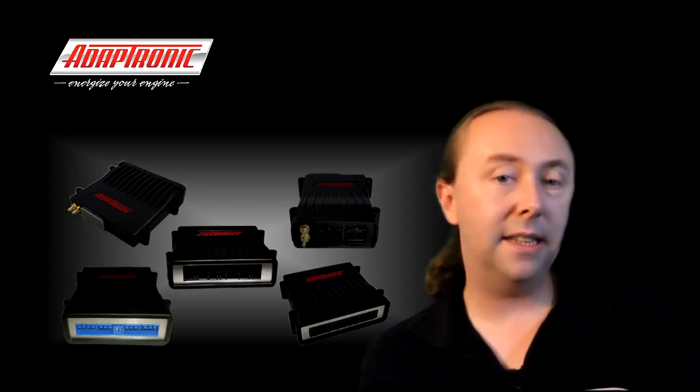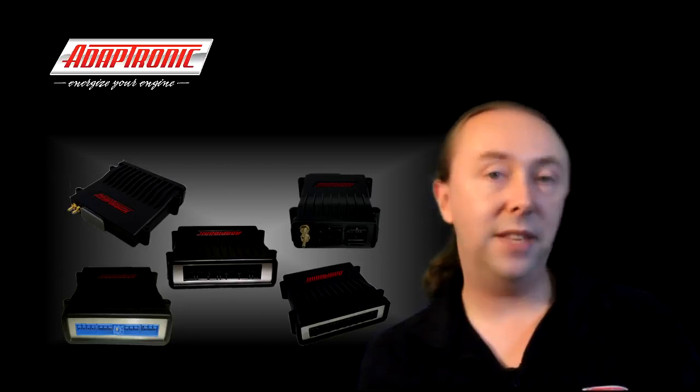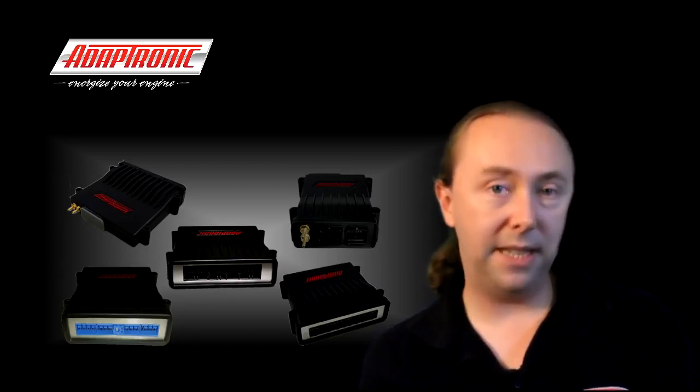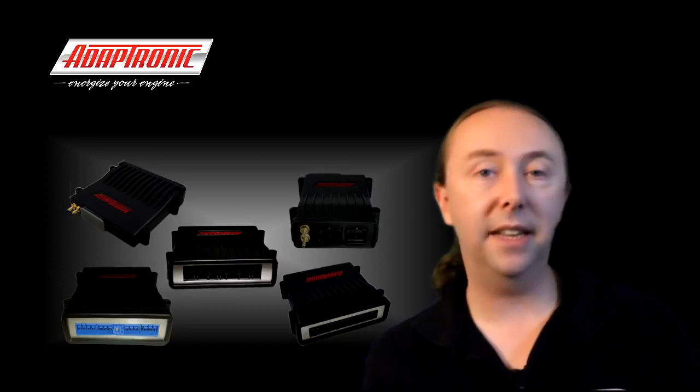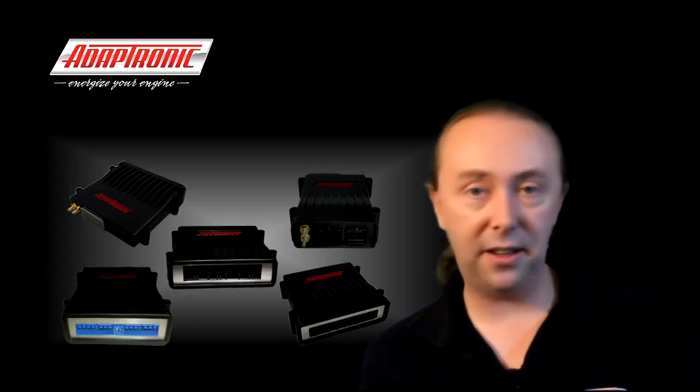But what it means is that if you're trying to deliver less than about 25 microliters of fuel, that's going to be very hard to achieve with this particular injector. And this is what happens when people say your injectors are too big to get decent idle or whatever.